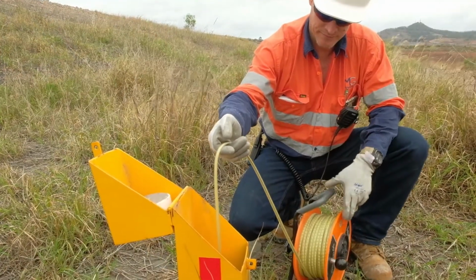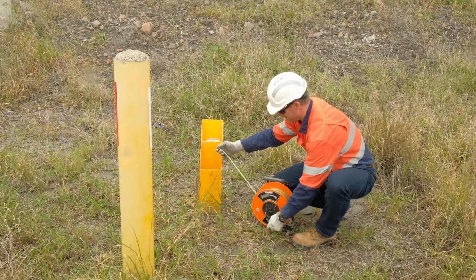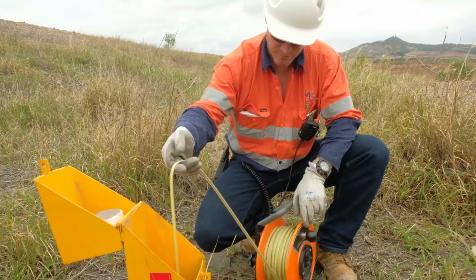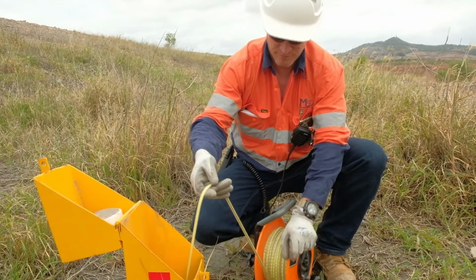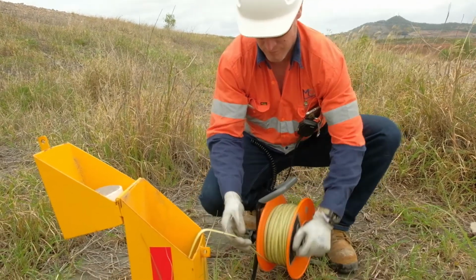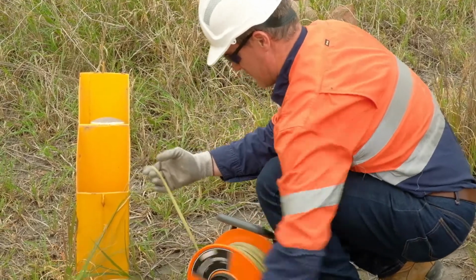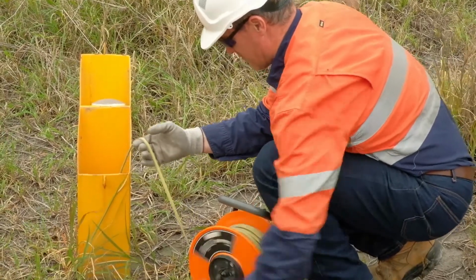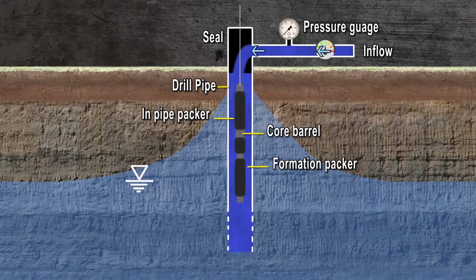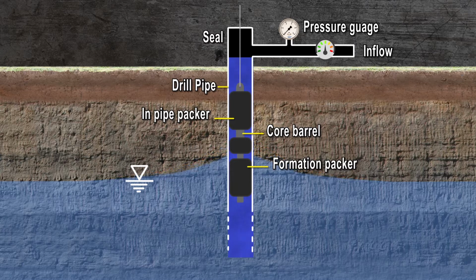Hydrogeological data can be acquired from standpipes and piezometers drilled at strategic locations around current and future excavations. Standing water levels may also be estimated from sonic logs if holes were not artificially filled with water during the exploration and geophysical logging process. Hydraulic conductivities can be measured using airlift, pumping or packer tests ahead of excavations. Hydraulic measurements should be acquired for the different rock mass domains encountered and not simplified or averaged.